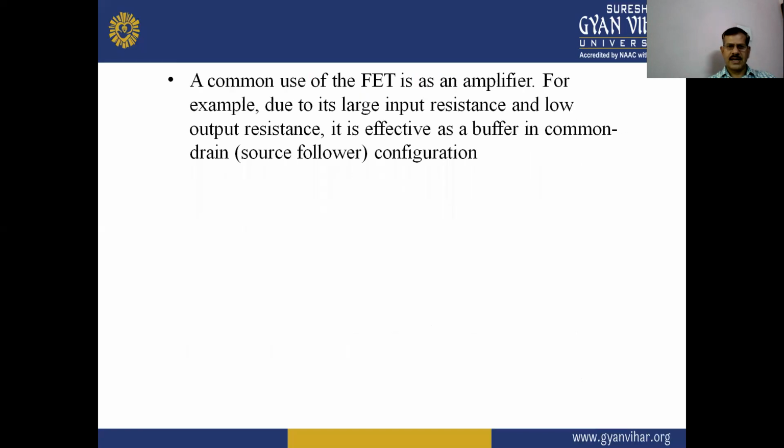For example, a common use of the FET is as an amplifier, due to its large input resistance and low output resistance. It is effective as a buffer in the common drain, source follower configuration. So these are some applications of this field effect transistor device.